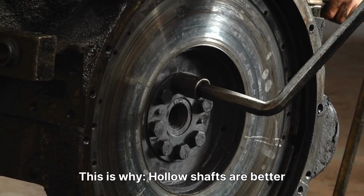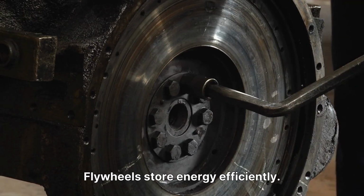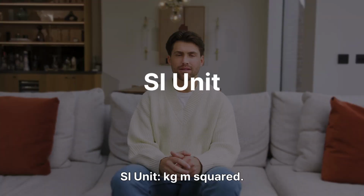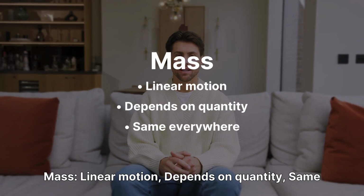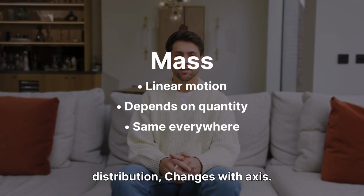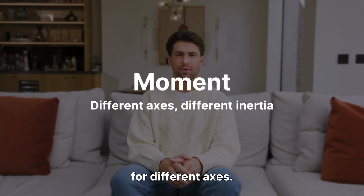This is why hollow shafts are better than solid shafts. Flywheels store energy efficiently. Wheels have rims. Turbines spread mass outward. SI unit, kg m². This tells us mass distribution, not just mass. Mass, linear motion, depends on quantity, same everywhere. Moment of inertia, rotational motion, depends on distribution, changes with axis. Same body, different moment of inertia for different axes.